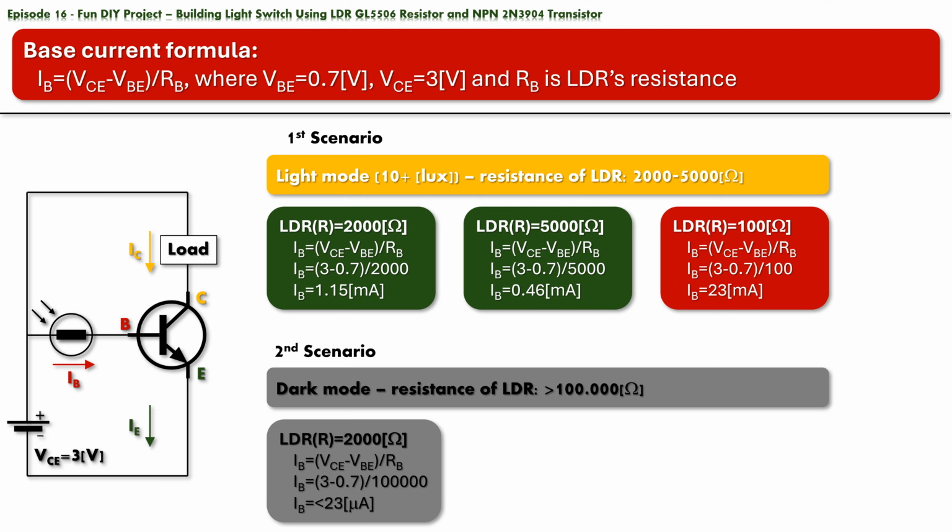few dozens of microamperes. From previous videos, we know that HFE parameter for 3 volts of VCE is around 179 to 194, depending on type of measurement taken. For simplicity of calculation, we will round up HFE to 200. Also have in mind, that for this particular type of transistor, maximum sustained collector current is 150 milliamperes. Let's do the analysis.